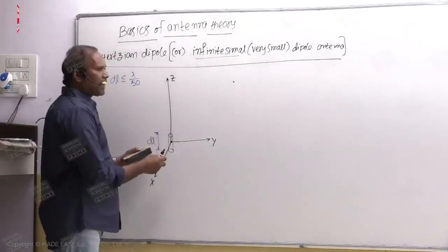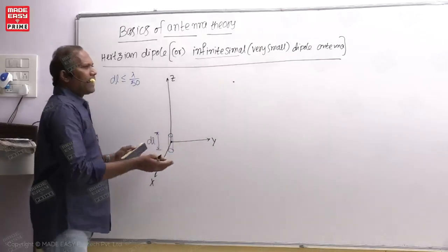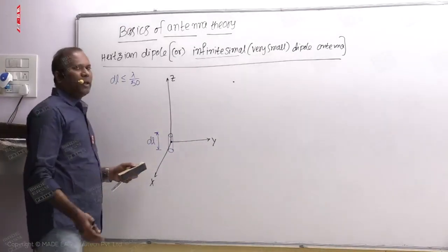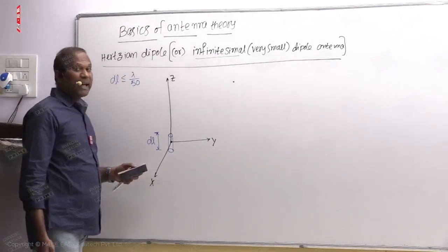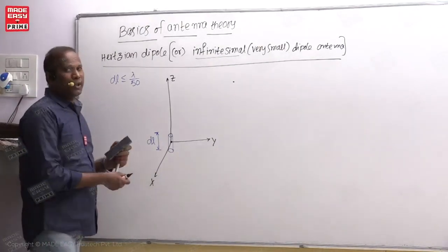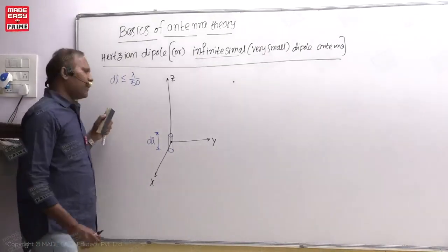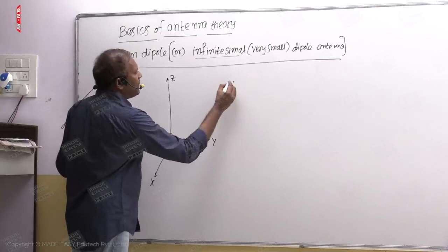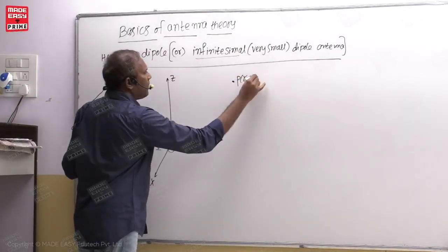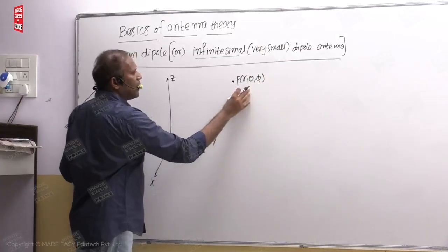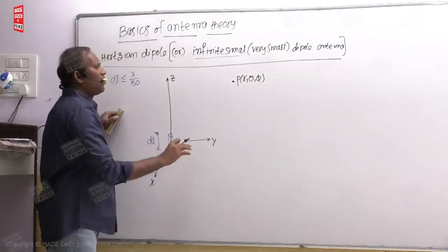Because any shape of antenna, it radiates energy, and after 5 kilometer, 10 kilometer you will be going and talking, for that location that antenna can be considered as a point source. So problems are easily solved in the spherical coordinate system. Now in the spherical system, the point (r, theta, phi) is a general location which represents all locations in the universe.